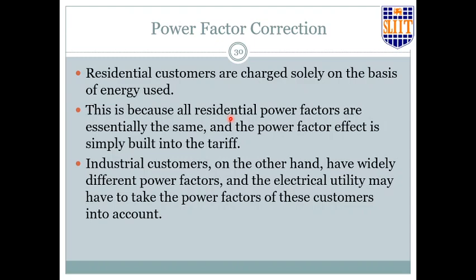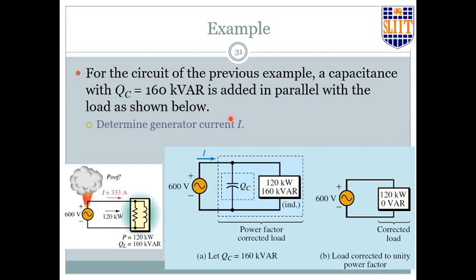So they have a ruling saying that if you have a company, a factory, the power factor has to be controlled at a certain level, maybe 0.85, 0.9 or so. If the power factor is less than that, they charge an extra penalty on the customer, right? They do that because they have to generate that amount of power if that exists, right?